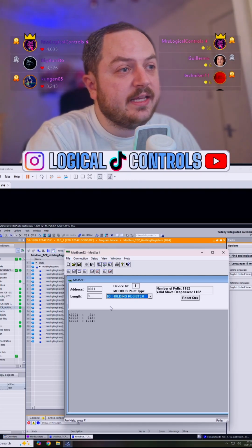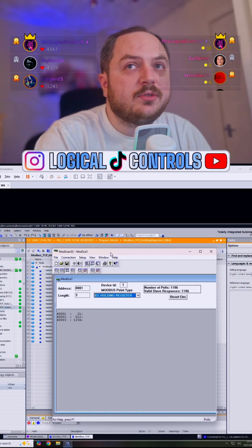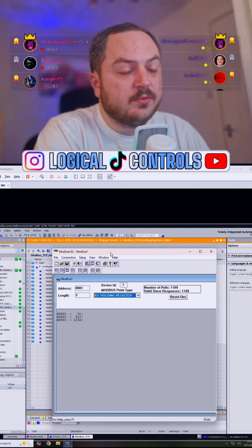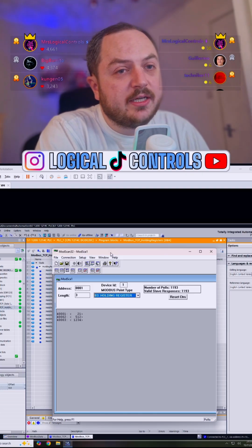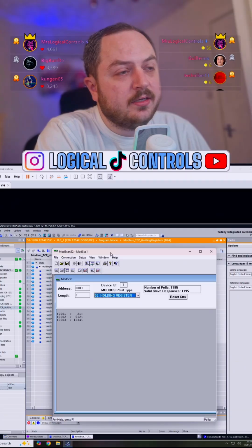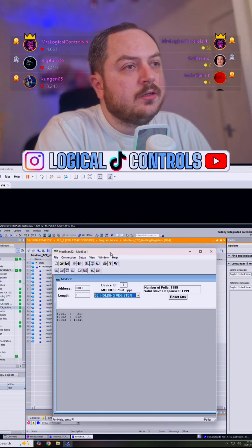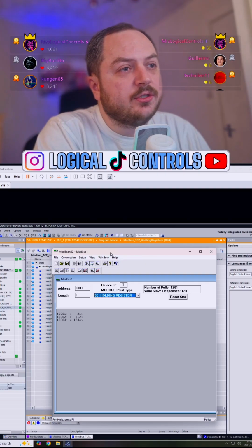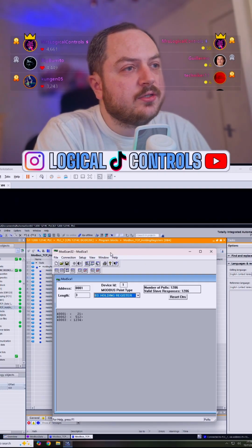There's an Ethernet cable, a Cat6, between the two. So Modbus comes in two forms: RTU and TCP. RTU is a screened cable, a differential pair as well, I think, and it's a serial communication. Whereas what I'm doing right now is Modbus TCP, which is a TCP connection.